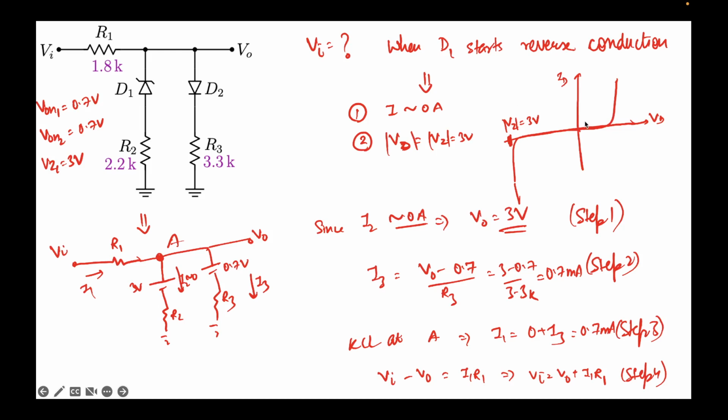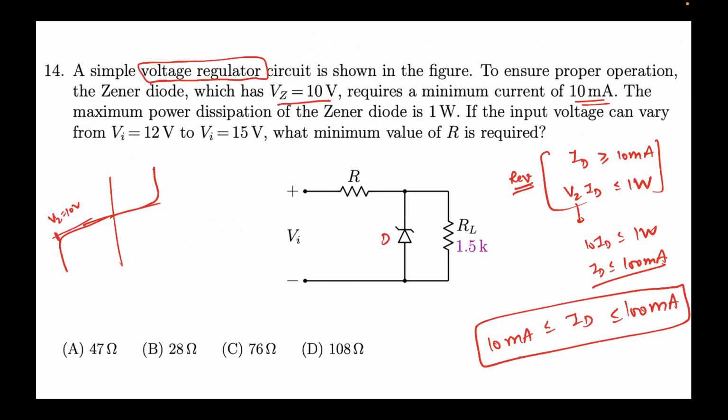So when you say voltage regulator, for instance let's say 10 volts, if there is an internal resistance also, some voltage would be dropping. However, when you operate in reverse bias, that internal resistance is very small. It's orders of magnitude smaller than your forward internal resistance. By looking at the graph, it may seem that the first quadrant and third quadrant are equivalent. Yes, in this model they look equivalent, but in reality there is a slope associated with this, which is much larger than the slope associated with that. Hence it's better to use it in this configuration. Okay.